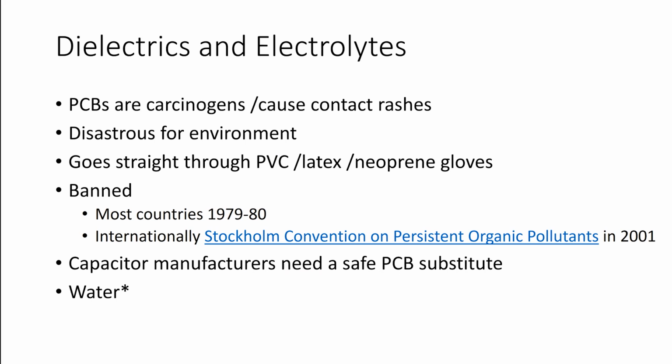They were used, apart from in capacitors, in transformers. You know, the big substation transformer at the end of the street? Those have all been replaced in the past 20 years to get rid of the PCB ones because they were a risk. It was the cooling in those. The great big coils were cooled by being filled with PCBs, and there used to be a big cylindrical header tank of PCB on these at the end of every street, and those all had to be gotten rid of. They're also used in electronics for arc suppression, leak detection.